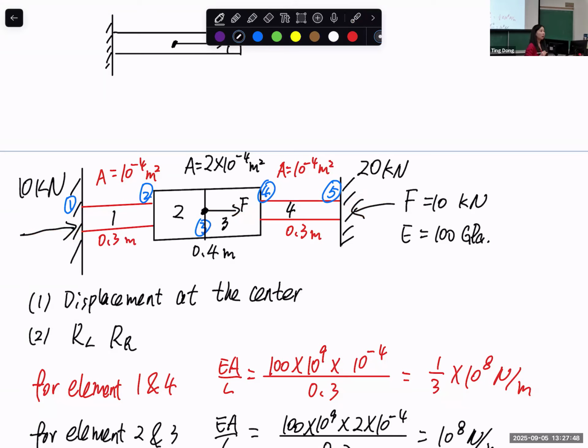How can you generate a moment? Your force is in the direction. It would be 5 kilonewtons. Do you want to explain? The force is distributed between the 2 points, and since it's right in the middle, it needs to be distributed evenly across the 2 points. Yes, the key information is that the structure is symmetric. So thank you. It should be 5 kilonewtons.